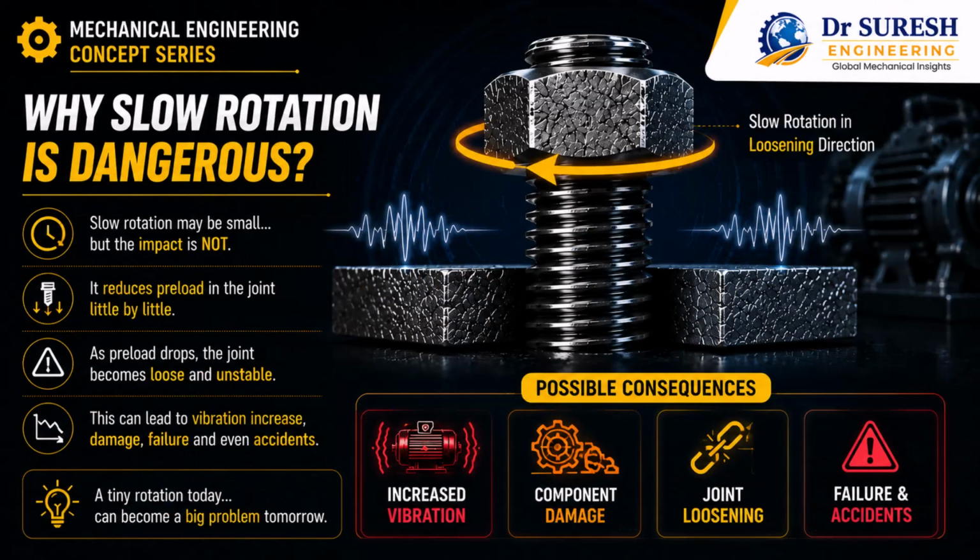Why is slow rotation dangerous? At first, the movement may appear extremely small, but the impact is not small at all. As the nut slowly rotates, the preload inside the joint begins to reduce little by little. And when preload decreases, the clamping force also drops. Now the joint is no longer fully secure. It becomes loose, unstable, and more vulnerable to vibration.